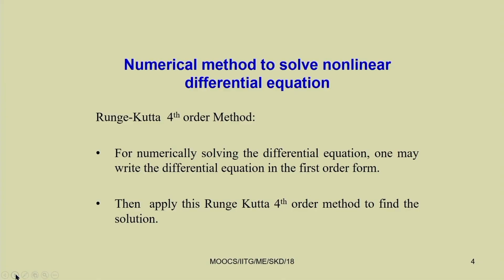For example, you can use the Runge-Kutta fourth order method, or you can use the codes available in software packages like MATLAB. You can use ODE45, and if you have a stiff equation you can use ODE23, or other software for different types of nonlinear equation solvers.